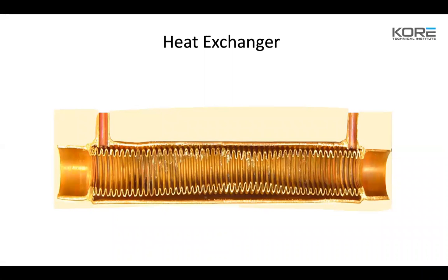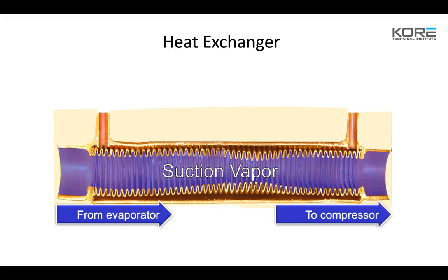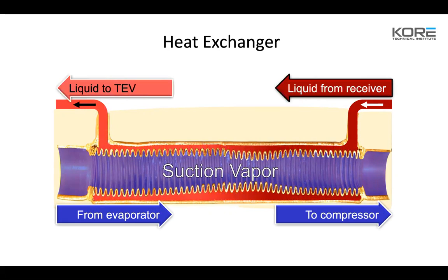So here's the inside of a heat exchanger, kind of what you were talking about, Tom. You've got your suction line, suction pressure that runs through the middle of it. It's got an outside section where the liquid line goes through around the suction line. So the suction vapor absorbs added heat from the liquid and then sends it right to the expansion valve. Usually when you're dealing with an inline, it's fairly close to the metering device, and it's usually inside the cooler.